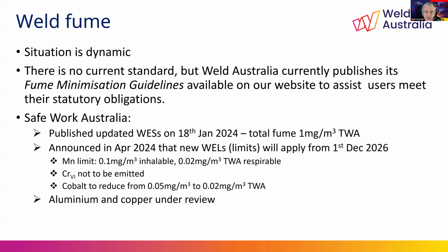Now, in April of last year, Safe Work Australia announced that from the 1st of December 2026, these exposure standards, or WESs in short, would be replaced by exposure limits, or WELs, W-E-L-S. Specifically, there will be a reduction in manganese exposure and limits on both the inhalable fraction, which will be 0.1 time weighted average, and respirable fractions, or 0.02 time weighted average.